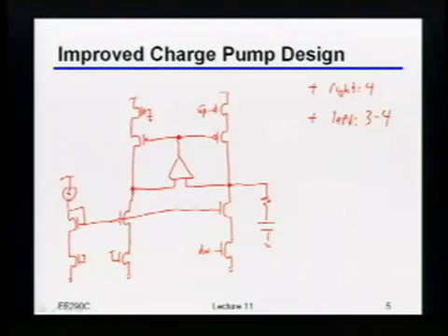Is it just the bandwidth? Making it asymmetric, right? Okay, it is asymmetric, and what does that output filter do to that side? It's going to reduce the impedance. There we go, it's dropping the impedance, right? Now, by the way, it's actually even better than that, because remember, there's a PLL here.